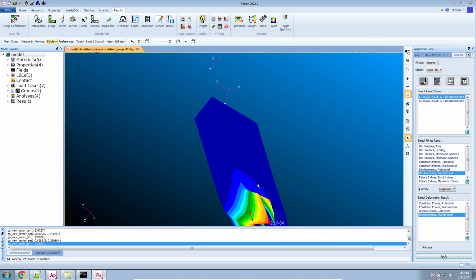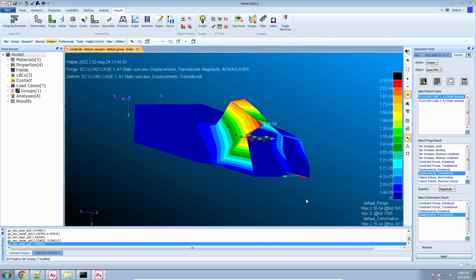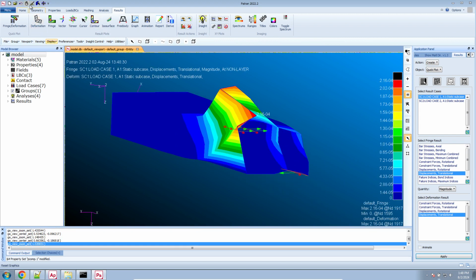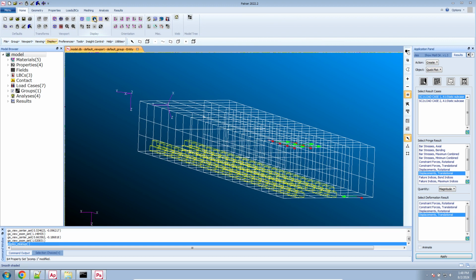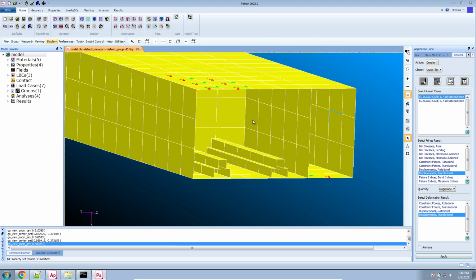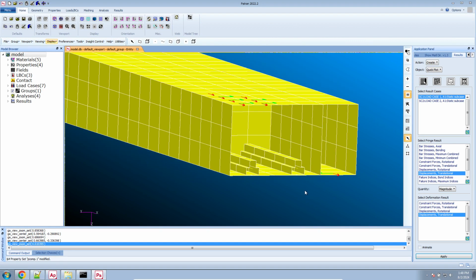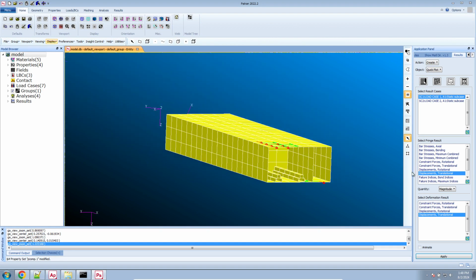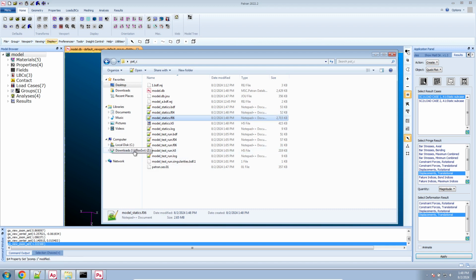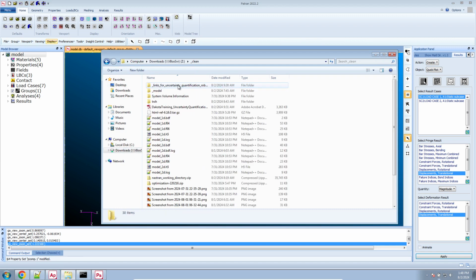So this is what the displacement looks like. It looks a little odd. I believe the reason why the displacement looks off is because in this region, there's nothing to stiffen this region. So that's why that's happening. And now let's go ahead and take a look at the failure indices. A quick comment about the failure indices. You might be, how do I say?